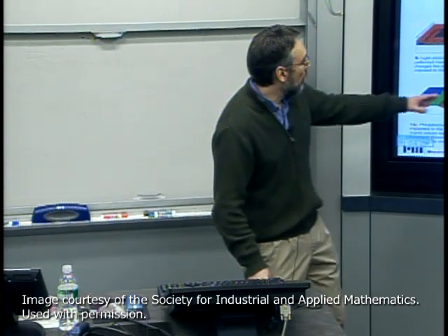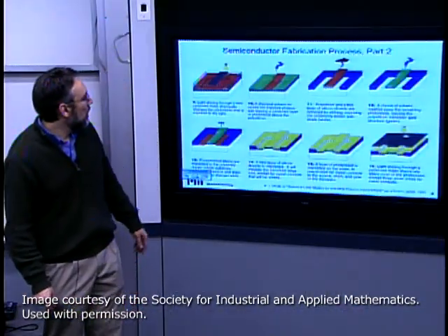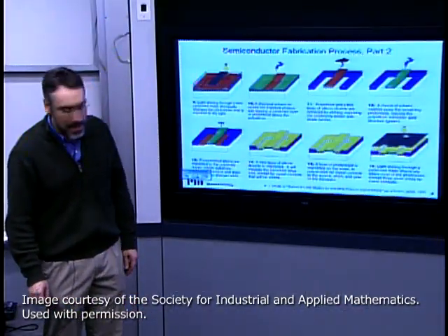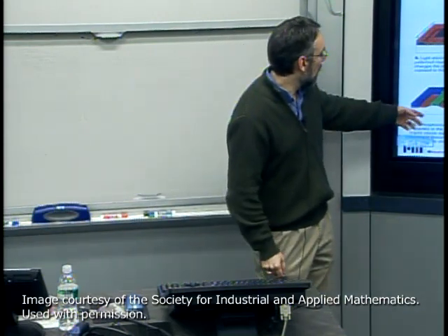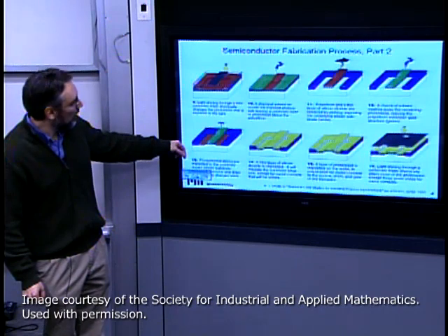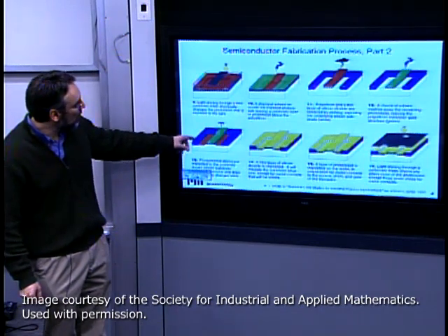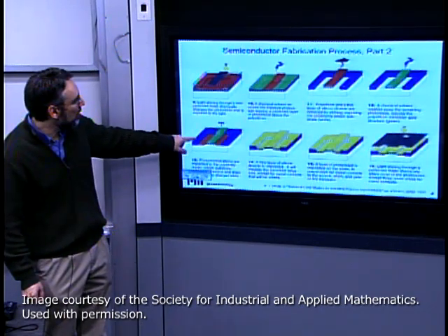What we're going to do now is another photolithography step here. Essentially, what we want to do with this yellow layer is build up an insulating layer. So I think a new layer of silicon dioxide is deposited. In this case, it's not thermally grown through that chemical reaction of oxide and silicon because I've already got polysilicon. I've got, well, I guess it actually might work in this case. I've already got a very thick layer of silicon.